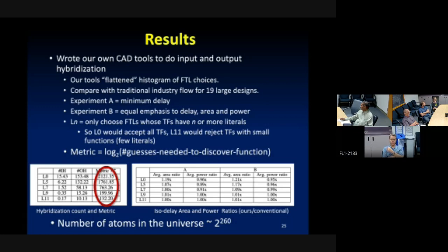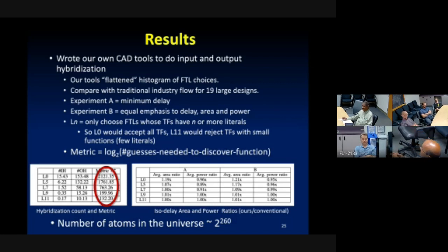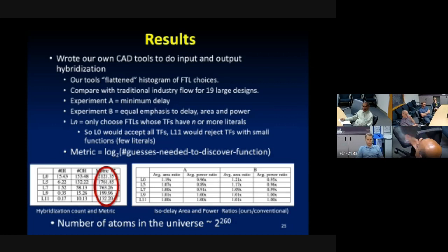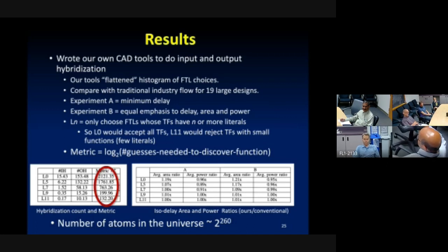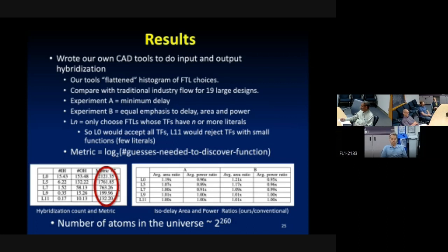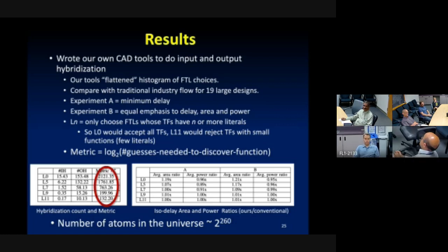In terms of cost to fabricate, is it comparable to traditional CMOS? Good, a super question. So Flash is a handful of processing steps in the recipe more than traditional CMOS. In other words, you do your CMOS processing at the foundry, and then a few more steps are needed to flashify it, if you will. So it is more expensive, but not insanely more expensive, just a handful of layers. So 5-10% more expensive, or something. Which is also why this has existed forever.